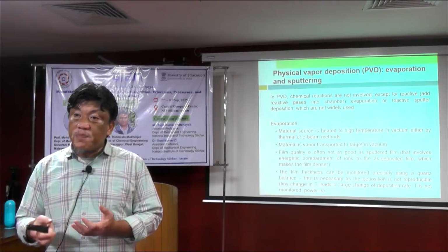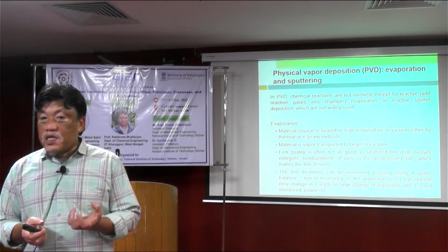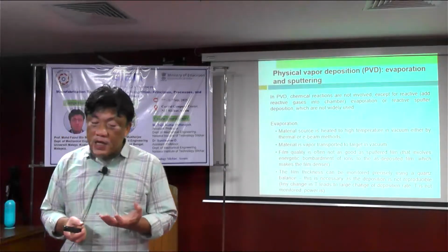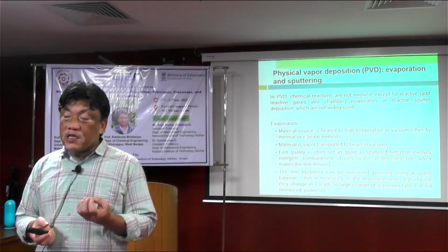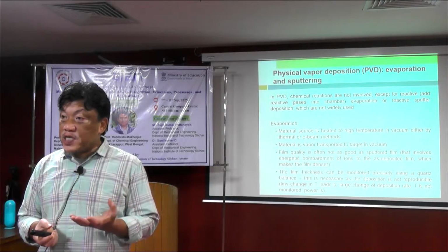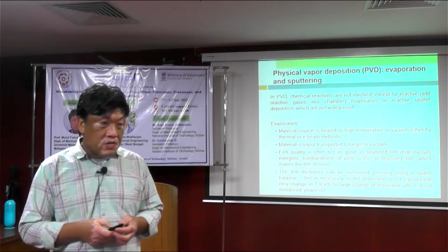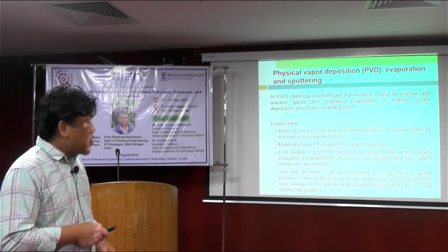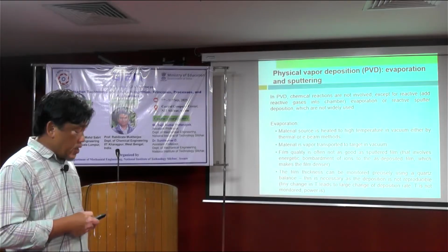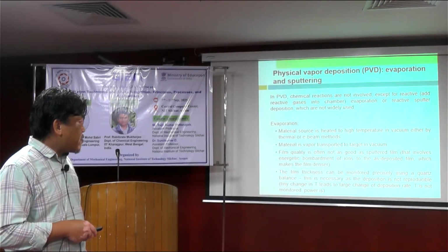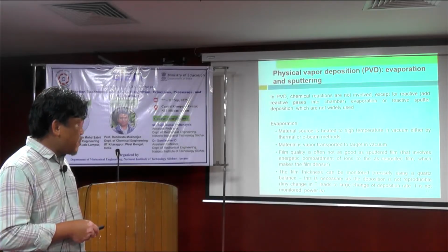So we control the power, not the temperature, whereas the temperature is the main parameter that directly controls the evaporation of the materials. So in order to monitor the thickness of the deposited material, we have to have a different way of monitoring it.